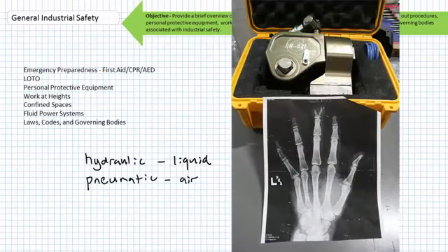At no time should any portion of your anatomy enter the region of travel. Once a hydraulic cylinder extends, it often does so with tremendous force and will punch through metal, not to mention flesh and bone. A commonly used tool in the wind turbine industry is something called a hydraulic torque wrench, which uses an actuator arm that often pushes against the tower wall to tighten a nut. Woe to those individuals that place their fingers between this arm and the tower wall. Be aware of pinch points when using such tremendously powerful tools.